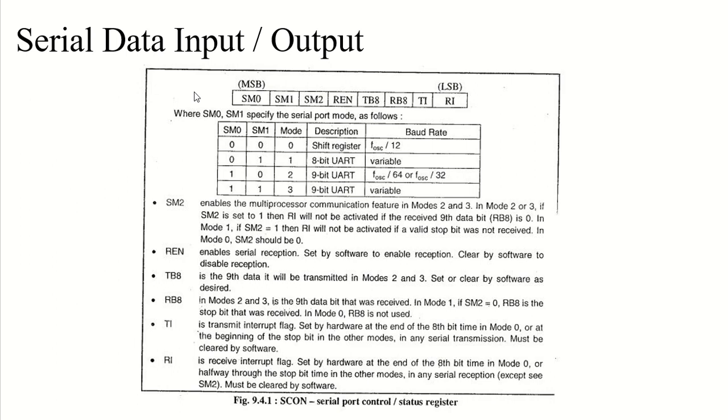And this microcontroller 8051 has a serial data communication circuit, which uses a register in the SFR called SBUF to hold the data. The register SCON controls the data communication, the register PCON controls the data rates, and the SBUF register comprises two registers.